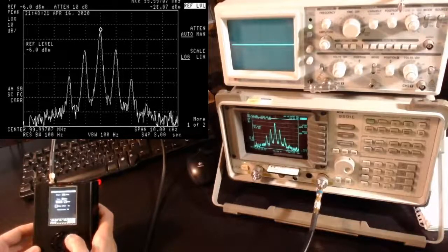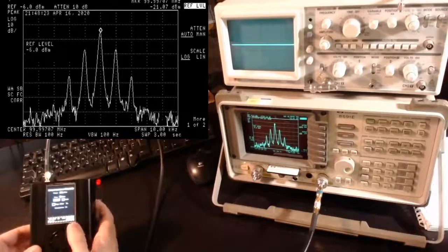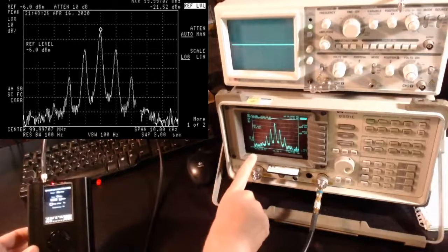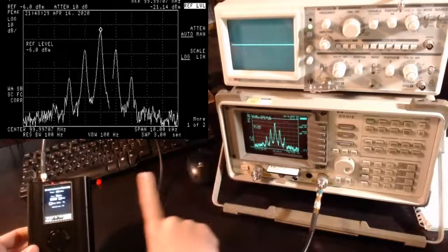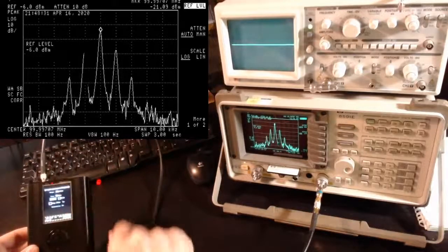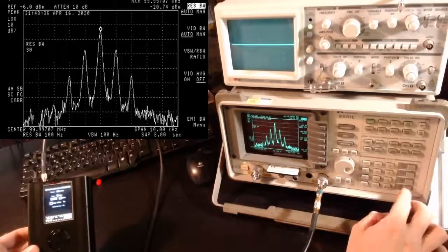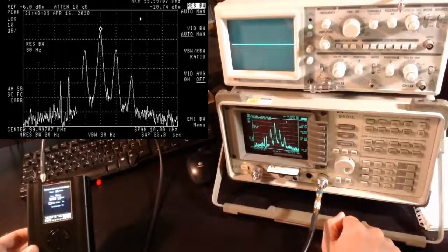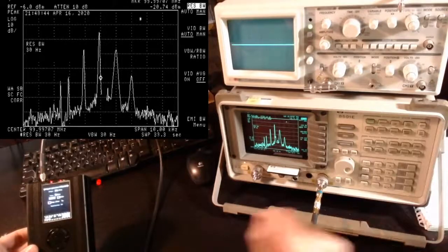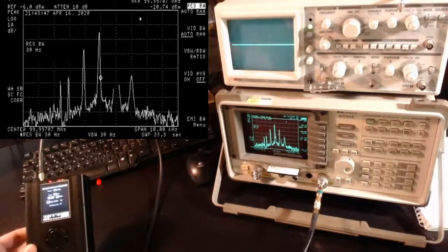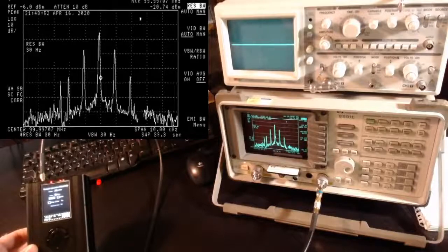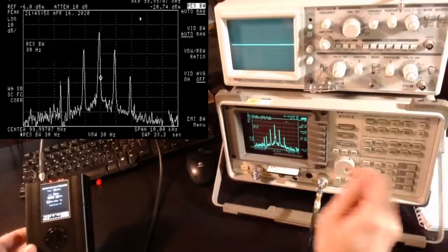And there we see the typical response of an FM signal. So at the moment, the resolution bandwidth is set at 100 hertz, so you can see it here. I'm going to improve this to 30 hertz, so we get even more resolution. And so we can see the typical shape. Now it's going to take 33 seconds to do a single sweep, but at least we can appreciate the typical shape of an FM signal with the Bessel function peaks that are exactly, well, let's see actually.